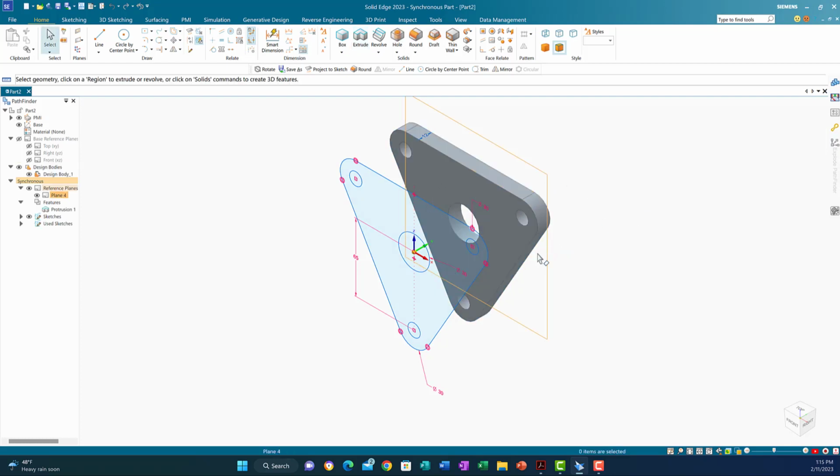Okay, so I was able to get this one. Now, the next step is I'm going to do rotate. I'm going to rotate this sketch 180 degrees. If I didn't create the solid model of the back, then because they are both copies of each other, they're going to rotate the same way, but now they are not connected anymore because we did, you know, that solid edge. Once you create the 3D, it wipes out the sketch that has been used and ignores it.